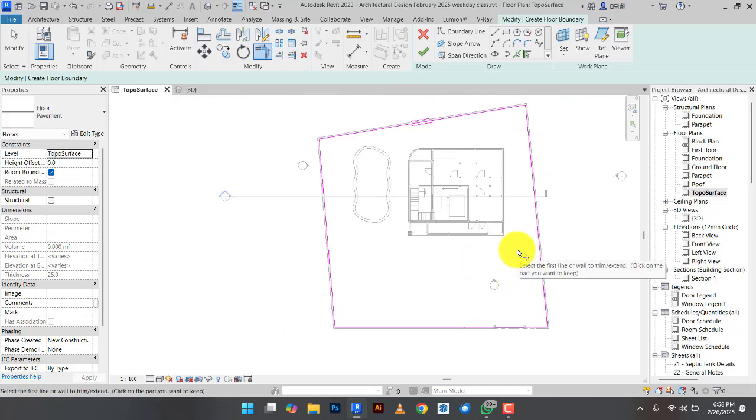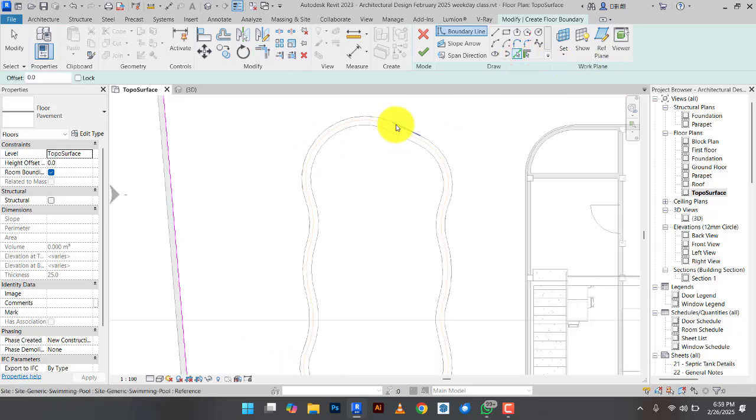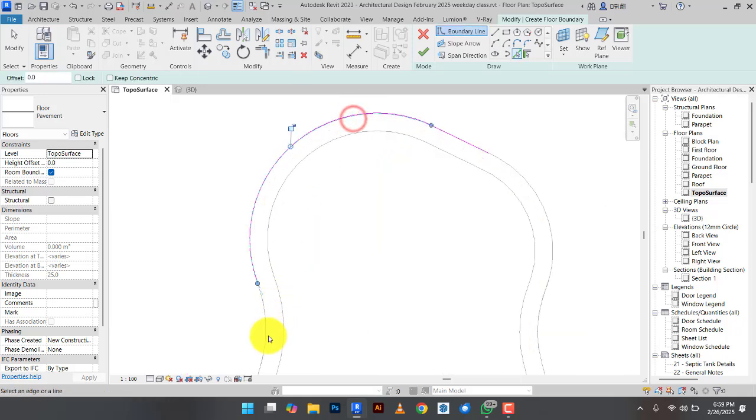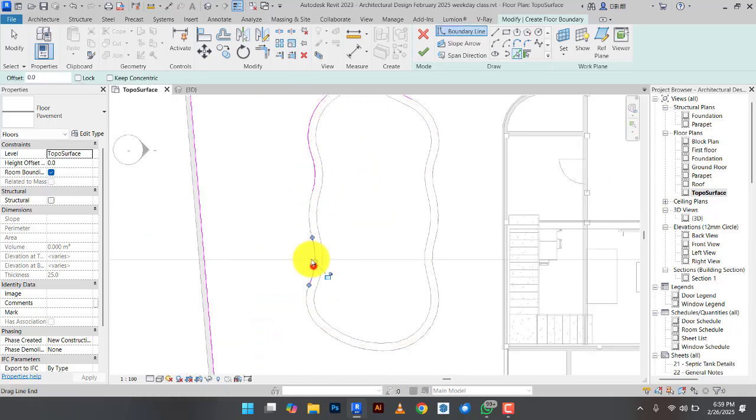Now what we've done is pavement on the whole land. So it means this will cover the pool and still pass under the building. But you can't pave under the building. So it means those parts we don't want, we have to cut them out to create that void. So after drawing the major shape, then select pick line. Then you pick the inside that you don't want to add. You get me? Good. You pick it out of the selection.